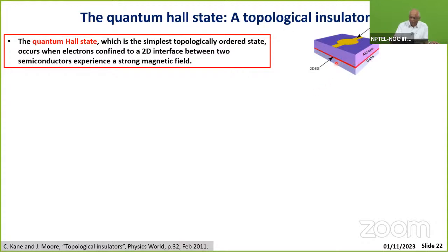Suppose you can trap a two-dimensional electron gas at that interface by doping the aluminum gallium arsenide with a donor atom like silicon. Since aluminum gallium arsenide has a higher band gap than gallium arsenide, the electrons will spill over to gallium arsenide, away from the silicon impurities that they were originally bound to in the aluminum gallium arsenide. So what that means is the electrons, which can be scattered by the silicon impurities, are now separated. So you have a trapped two-dimensional electron gas, which can have an extraordinary mobility.